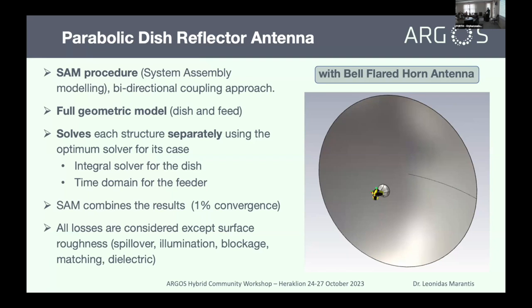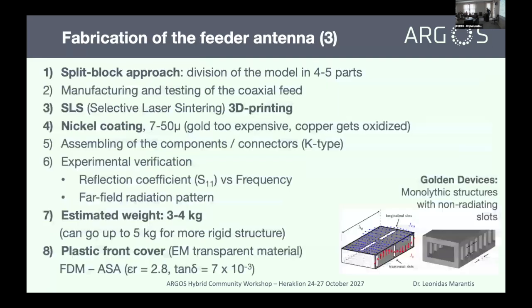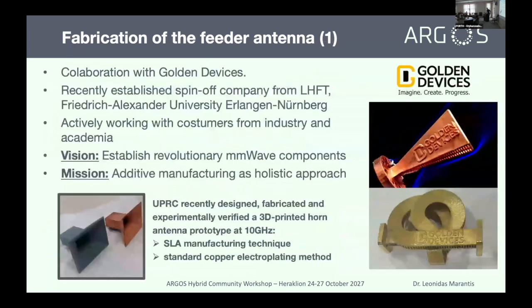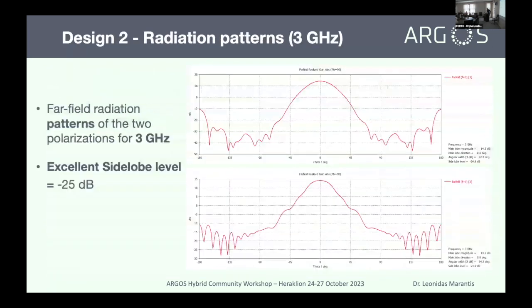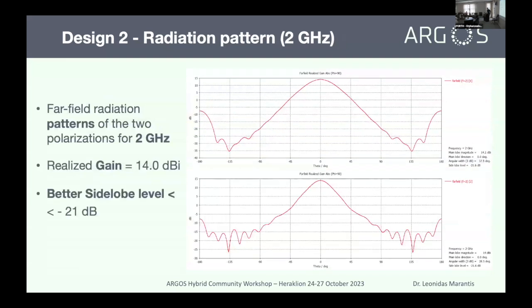Also, the reason I'm asking is I noticed that your 10 dB beamwidth of your field is around 90 degrees, with an edge taper angle of 120. So my question is, are you still considering a bigger front end, to design it differently? Because I assume your aperture efficiency is... you showed the spillover efficiency, but I wonder what your aperture efficiency is in this case.